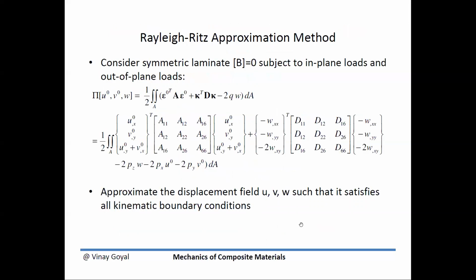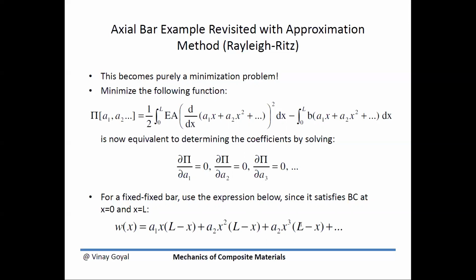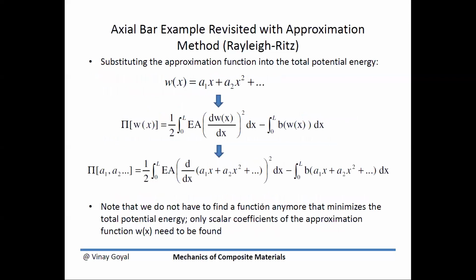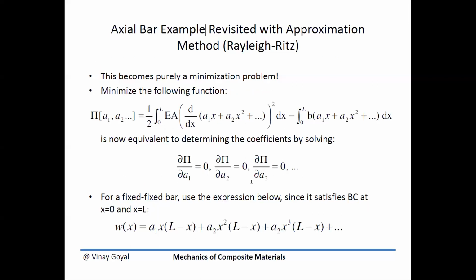So what if I want to apply the Rayleigh-Ritz? And by the way, I forgot to tell you, the method we're discussing here is called the Rayleigh-Ritz method. The purpose of today's lecture is to show you that energy methods can be used to derive the governing equations. And the second objective is to show you that I can approximate the solution to various problems using this idea, which Rayleigh-Ritz came up with, which is that instead of trying to find this function W that solves this, what if I take an approximation and plug it in? And then I can minimize pi with respect to these coefficients. That was the idea there.